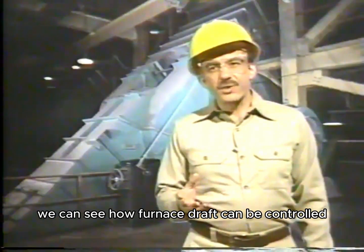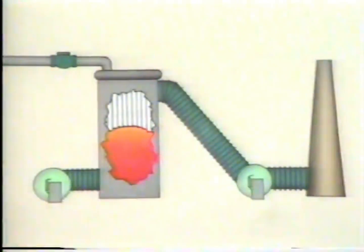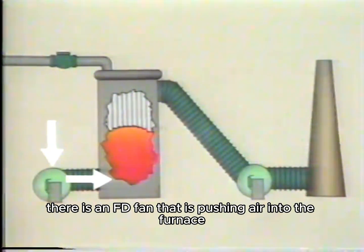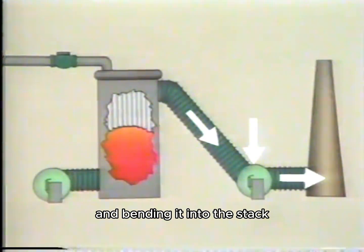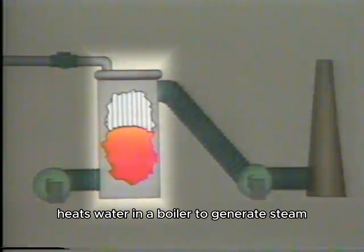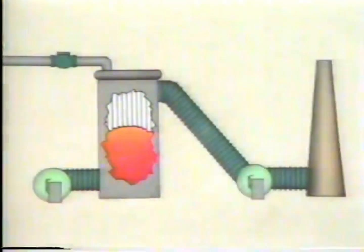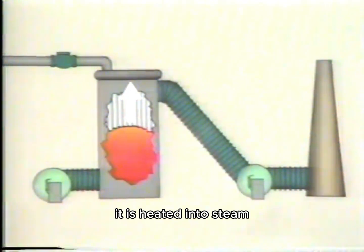We can see how furnace draft can be controlled using a simplified illustration of the process. In this illustration, there is an FD fan that is pushing air into the furnace and an ID fan pulling exhaust gases out of the furnace and venting it into the stack. The heat generated by fuel combustion in the furnace heats water in a boiler to generate steam. The inner walls of the furnace are made up of water wall tubes. As water flows through the tubes in the furnace, it is heated into steam.